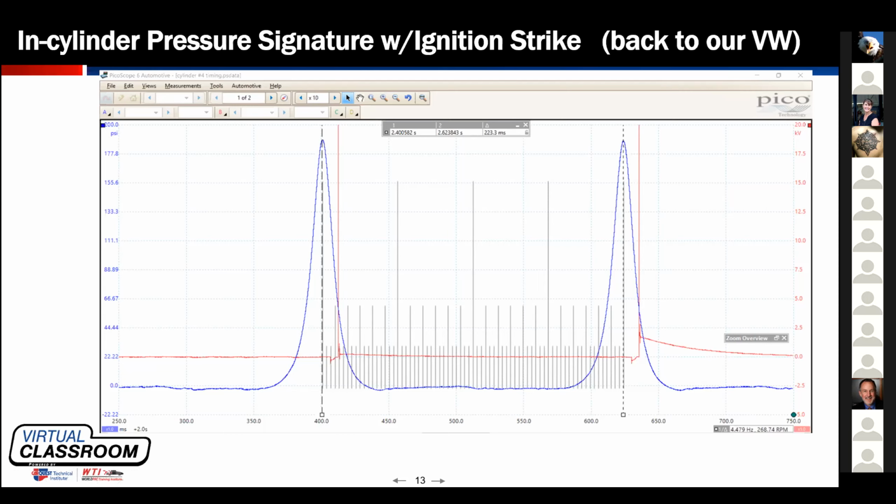This is what I consider to be a creepy number. When you deal with circles, there are creepy numbers. There are things like 0 degrees, 45 degrees, 90 degrees, 360 degrees, 720 degrees. There are some basic numbers that have a creepy factor to them. If I took the few degrees before top dead center and added it to the actual strike, I would realize that this ignition timing is 45 degrees after the true delivery, 45 degrees after that piston hit top dead center.